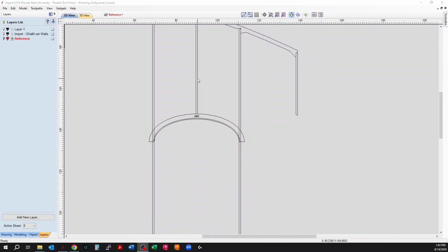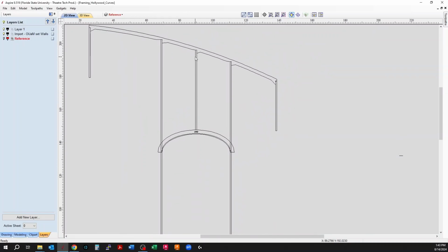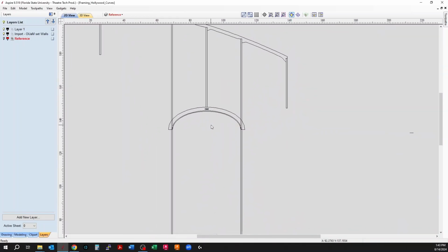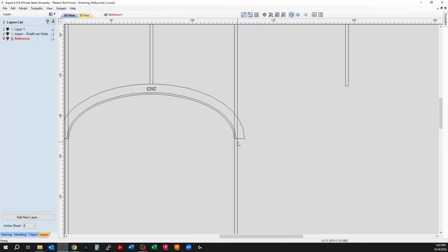You can see I've added another piece here, the same thing I was doing before. But for this piece, you see that we're going to go past this framing piece, or into this framing piece, which is great. We're actually just going to do like a dado notch into the framing on either side.